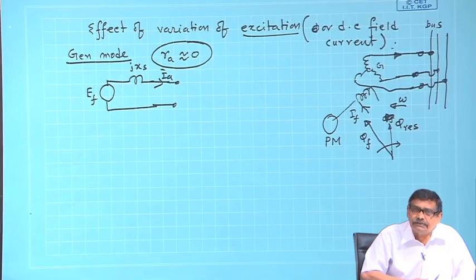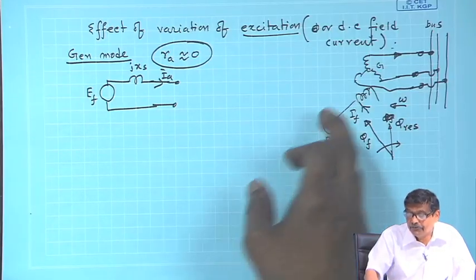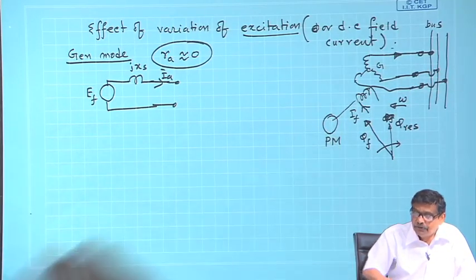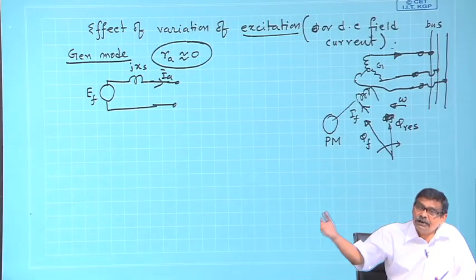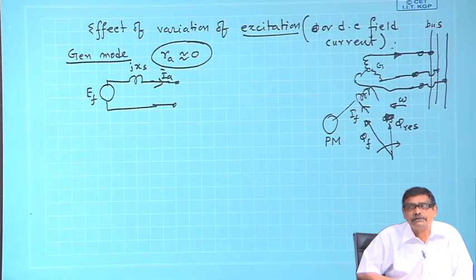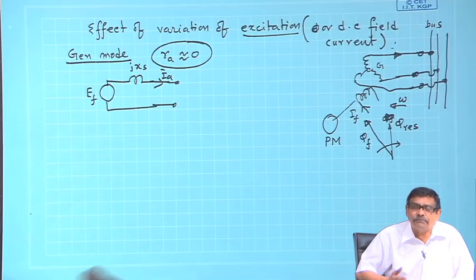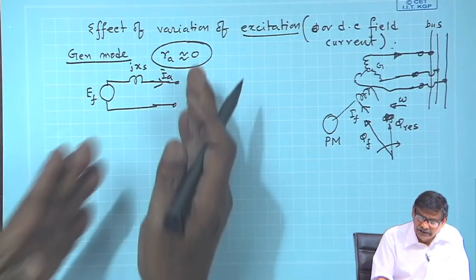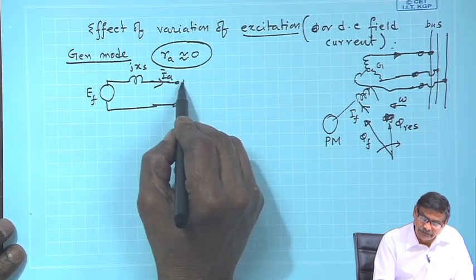So, this small generator in the laboratory, if you have synchronized it and increase the prime mover input, will also contribute to the total demand of the load connected to the bus by a small amount, some kilowatt, say, if it is a kilowatt rating machine. So, load is already connected there in the bus, and this voltage is V.